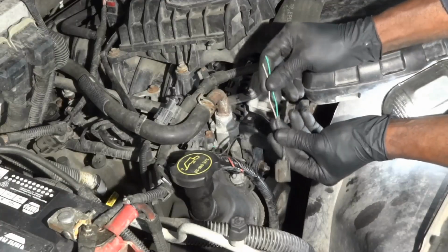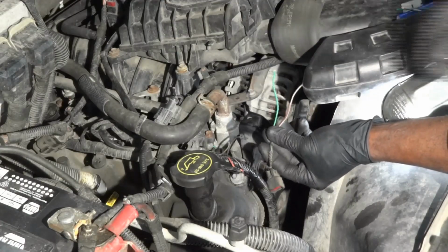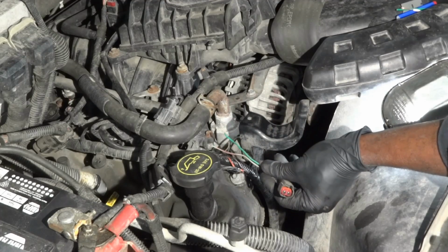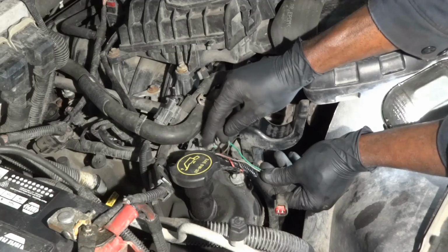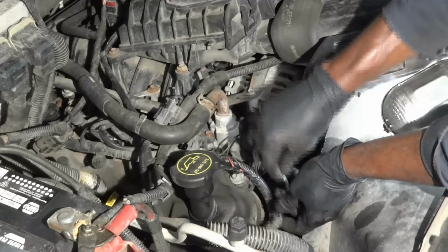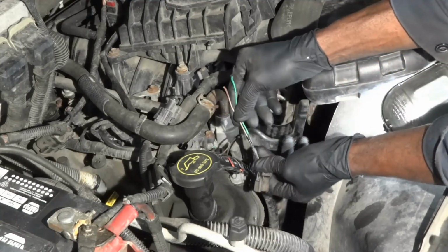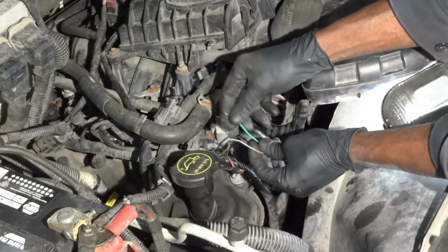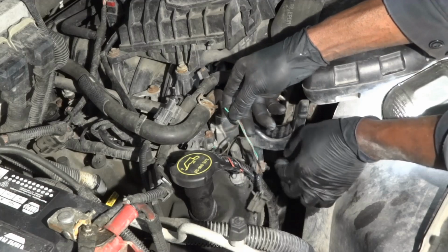The length of this connector over here is starting to look a little bit short. If I connect these wires straight to the wires on the harness, this connector is gonna be too short and there will be too much tension on these wires. So what I'm gonna do is I'm gonna lengthen these wires just a little bit.